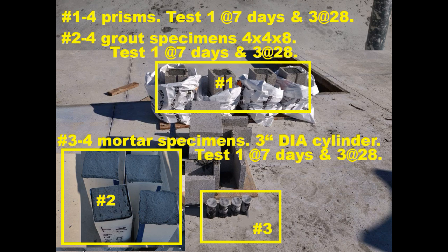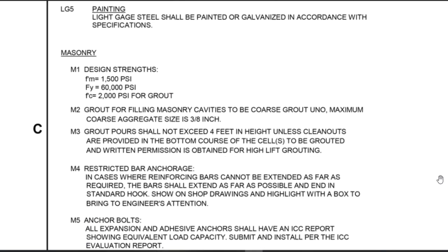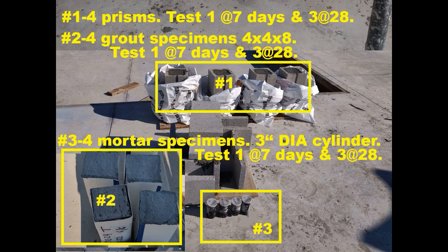Masonry in the area in question will be considered structurally adequate if the average compressive strength of 3 specimens is equal to or exceeds the specified value. Additional testing of specimens extracted from locations represented by erratic core or prism strength test results will be permitted.